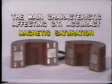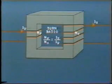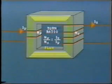What do we mean by this? Well, it's really a problem of overloading the core. The amount of magnetic flux circulating in the core of the transformer is, of course, proportional to the current passing in the primary. When primary load current increases, then magnetic flux in the CT also increases.